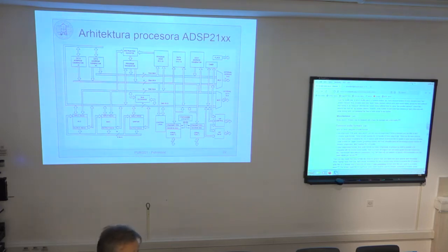So altogether you have 64 bits of instruction that is fetched simultaneously from the program cache memory. And since these instructions are independent, they don't have any hardware collision in the sense of resources, they can be executed in parallel. So this MAC instruction, multiply accumulate, is encoded with the first part of 32 bits, and the load or store instructions can be executed in parallel.